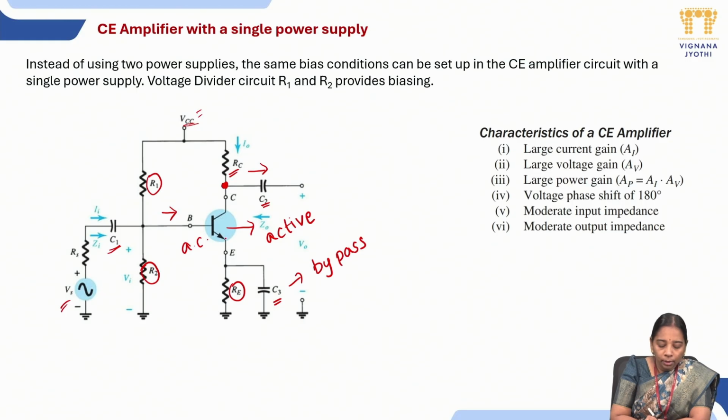The transistor amplified the input voltage to a maximum extent, and again it gets dropped across RE, meaning there is no meaning for amplification. And again it could be connected to the base as feedback also. So it is a problem if we have a drop across this RE.